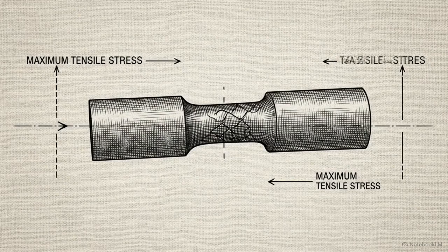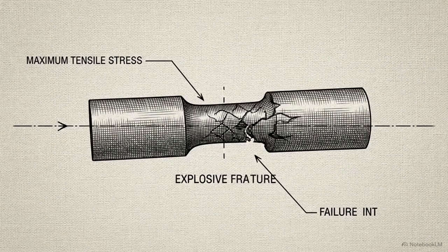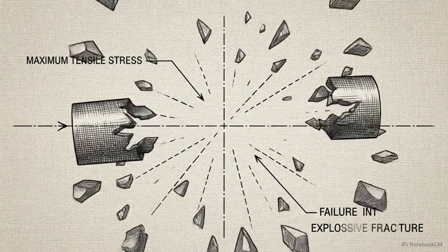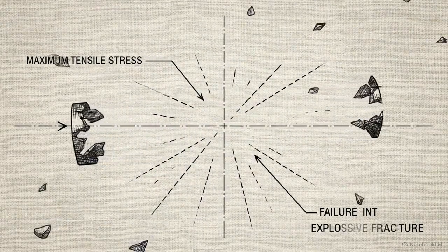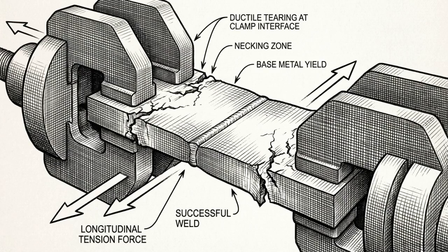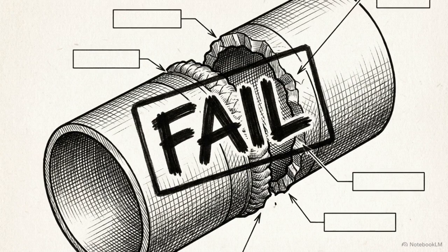Before any of those non-destructive methods are deployed in the field, the exact welding parameters must be proven in a laboratory. This requires destructive testing. Destructive testing intentionally breaks sample welds to extract physical data. Pulled apart in a tensile machine, the steel must snap in the base metal. If it breaks at the weld seam, the engineering procedure fails and is redesigned.